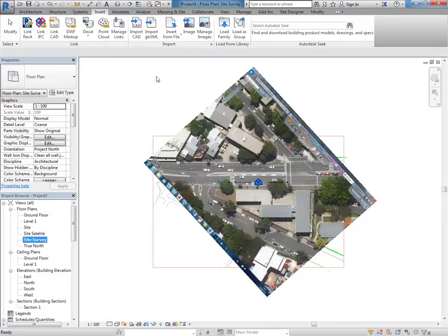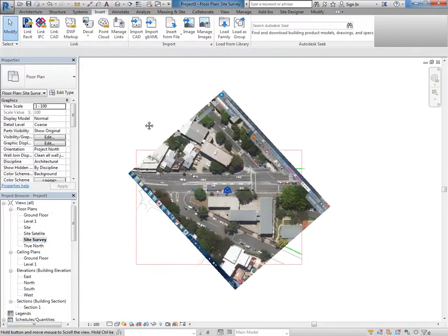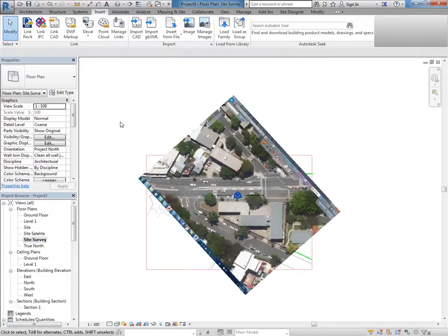And now, do you know how to adjust your visibility settings in Revit? A really good option that people don't use as much these days as they did before is this one over here, Visibility Graphics Overrides. It's got a long funny name because they've stuck that graphics overrides thing on, but it's really visibility. Everyone would use it if it just said visibility, but graphics overrides are something that you'll do sometimes, but the visibility is the more important thing.